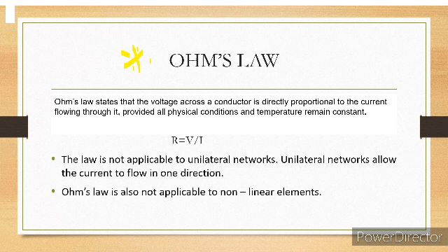So here Ohm's law states that the voltage V will be proportional to I. If you take R equals V by I, then for V the formula becomes V equals I into R. So it's nothing but V is directly proportional to I. The only restriction is that the temperature should remain constant.